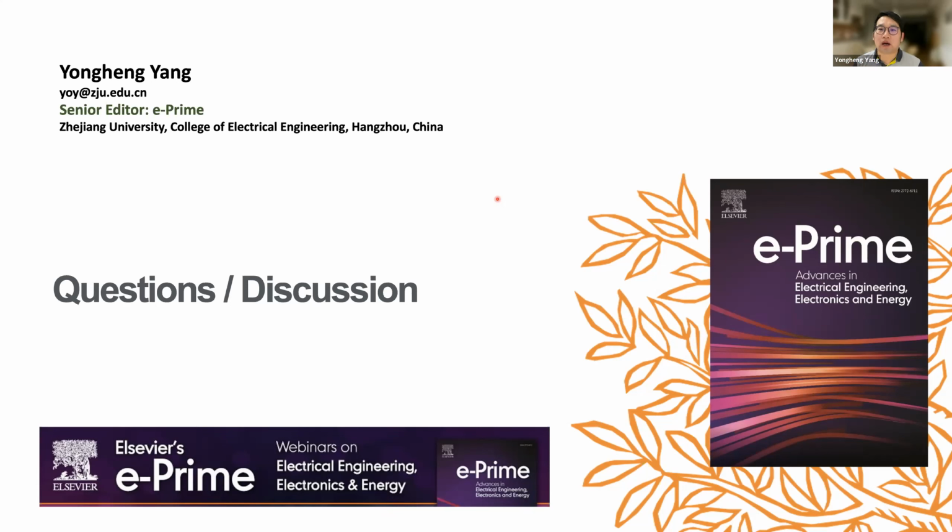But of course, there's always a double-edged sword, and if you have very high frequencies, we may face EMI, EMC issues in the power converters, and also the design of the magnetics, the passives. For example, if you are switching your power devices at megahertz or a few hundred megahertz, then the design of the magnetics can be a challenging issue. I hope I have answered the question properly.